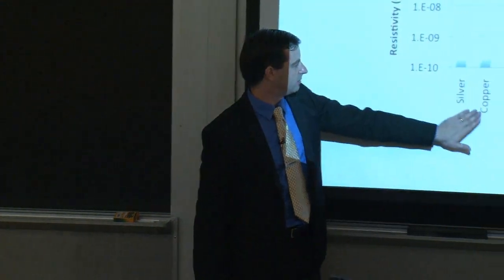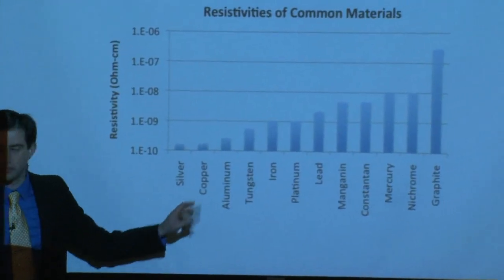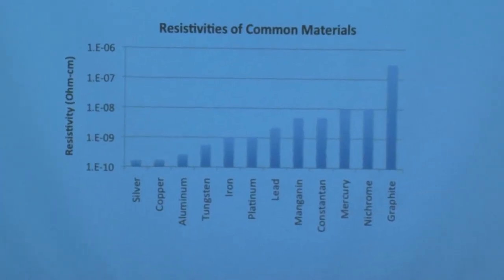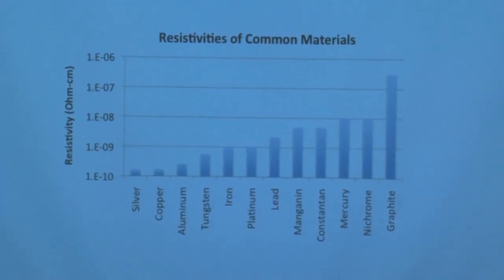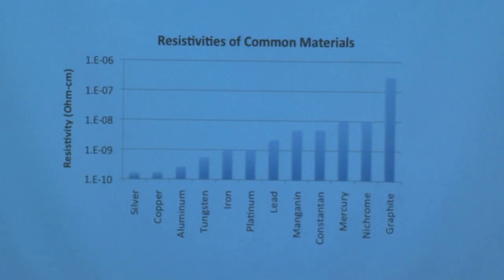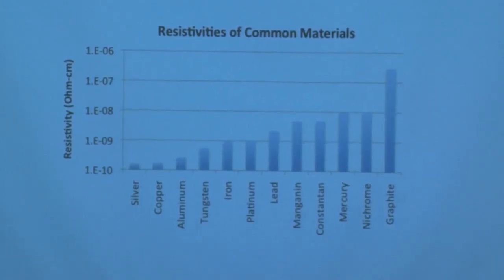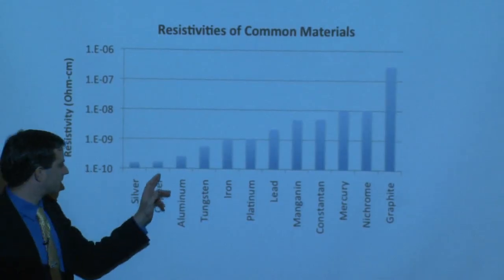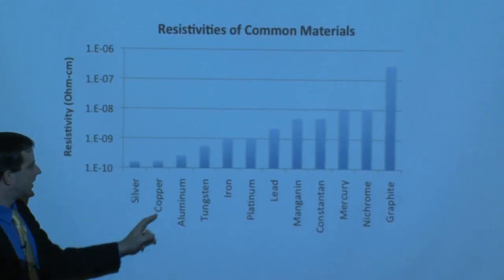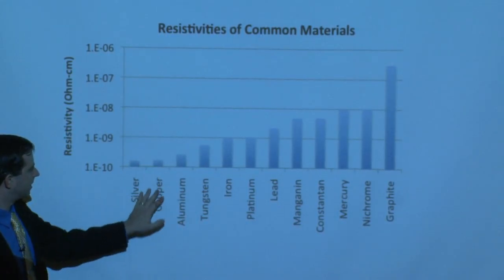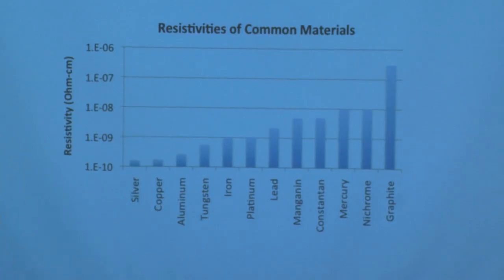And that's why you see folks looking at copper, nickel, which is similar in electronic structure. It's one element to the left of copper on the periodic table, and other metal alternatives. Yes? Where does nickel fall on this resistivity chart? I'd have to give you the exact number, but if I were to venture a guess, what you're noticing over here are several of the metals that fall in the noble metal category.